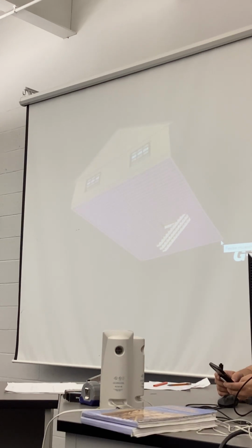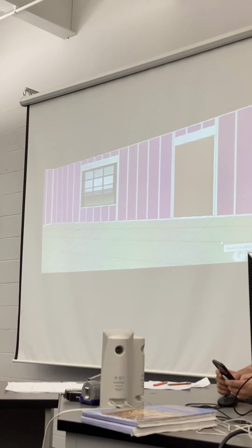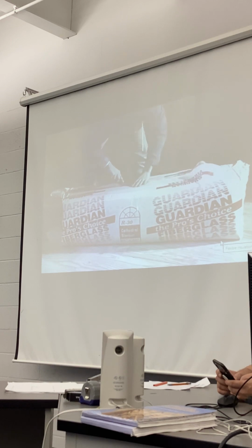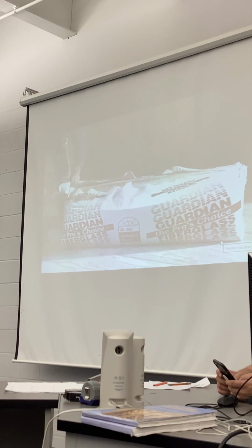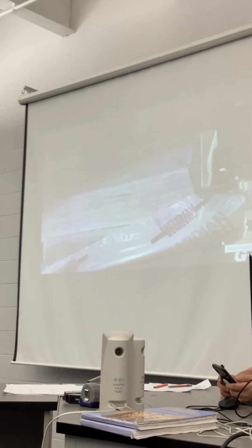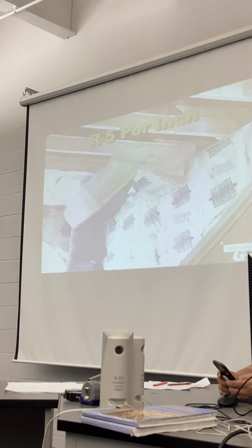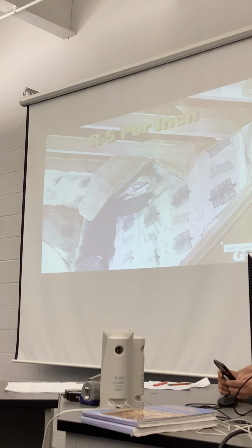Bat and blanket insulation is used to insulate below floors, above ceilings, and within walls. Generally, bat insulation is the least expensive wall insulation material, but it requires careful installation for effective performance. Flexible insulation comes in 16-inch widths, suited to standard spacing of wall studs and attic or floor joists. Bats and blankets typically have an R value of approximately R5 per inch of thickness.